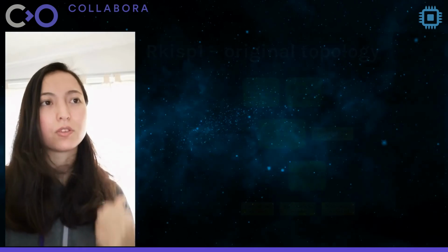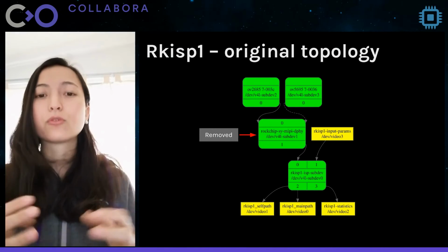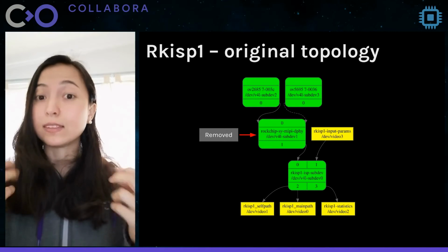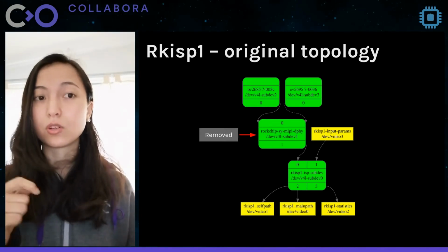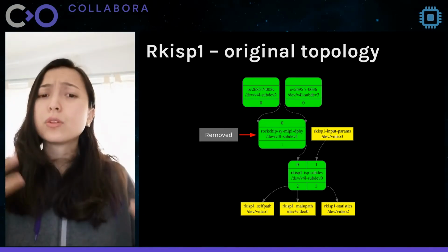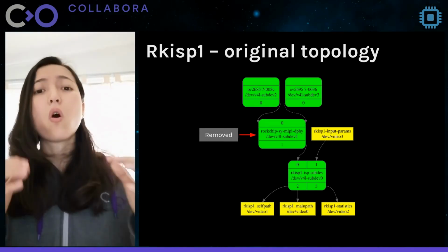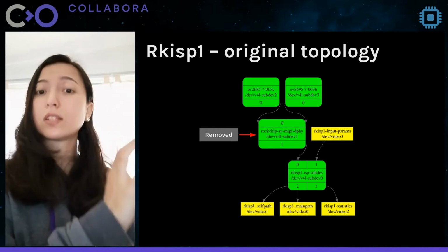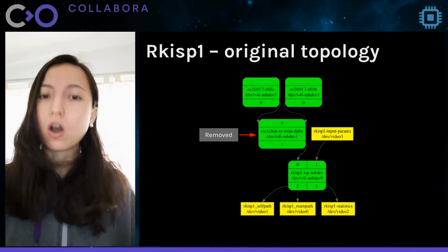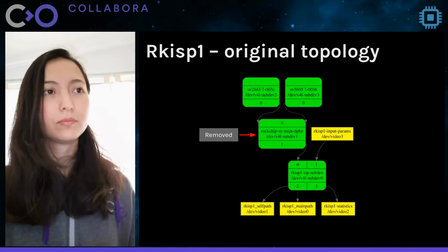So if we come back to the original topology, if we want to add support for the parallel bus, we would need to update topology dynamically, depending which bus you are using, replacing that block with the parallel block, which would be confusing for user space that needs to perform all the manual configuration, or we would need to expose another block to represent the parallel bus. And another block, more complex for user space. That's why we decided to remove it.